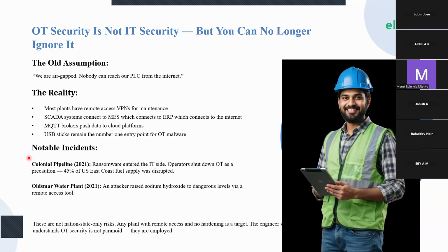At the factory level, for most PCs and devices we have to give remote access, and SCADA systems connected to MES and ERP systems have to be secured by default. So this kind of security that we have discussed already, certificate-based security and user-based security, like sign-in methods and role-based access. Once the operator has signed in with particular credentials, access to a particular value modification, like set point modification, must be granted only to those designated for it. Those are the security principles we have to keep looking at in industry.